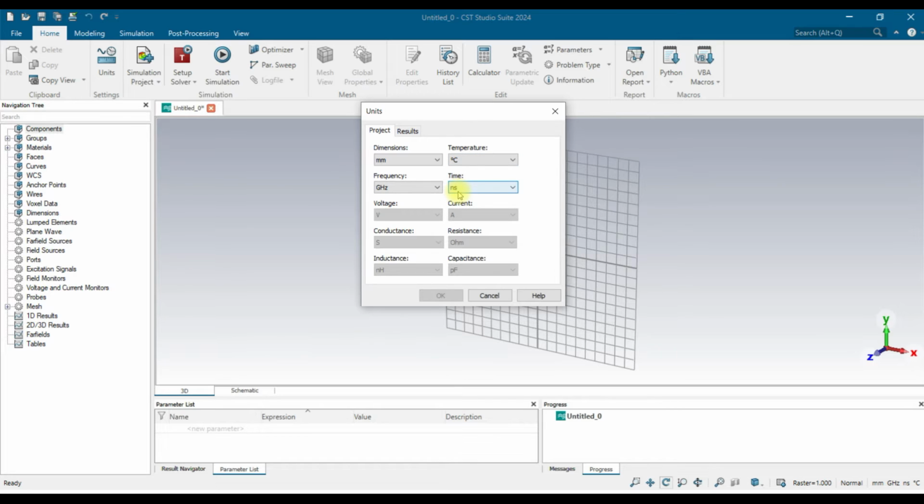As I mentioned in the previous video, once you start configuring CST you can see the measurement units, and we keep them as default. If you make any changes there and then come into the design dashboard, and you want to change those dimensions, you can do it here. For example, you can change millimeter to centimeter or any other dimension. You can also change the frequency scale to hertz, kilohertz, megahertz or terahertz accordingly. For now I'm keeping the default settings. So this is the units.